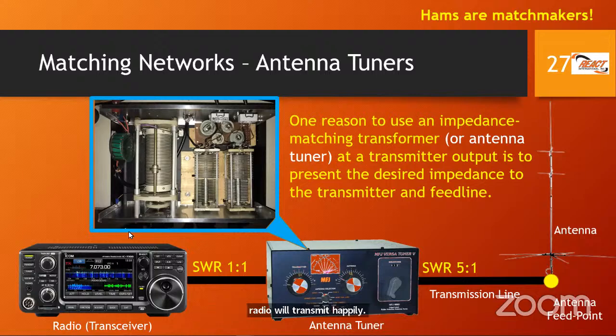So this is the setup here, and we have an exploded view. This is a top view of the inside of what this looks like. So you'll notice that we have some, these are two tuning capacitors, and this is the example of the coil that we are turning, and the capacitors that we are turning as well. We are varying the area of the plates, so therefore the capacitance is changing, right? So it's L and C again, L for coil and C for capacitor, L for inductor and C for capacitor. That's a matching network consisting of coils and capacitors, right? So see how the earlier theory is helping us to understand a little bit now when we talk about the components inside of there. See practical example of when we use these components in circuits to actually achieve something, right?